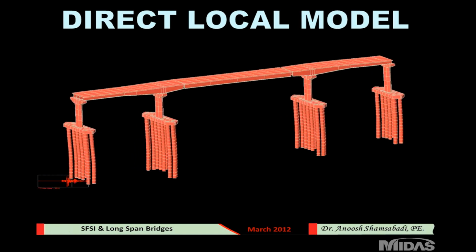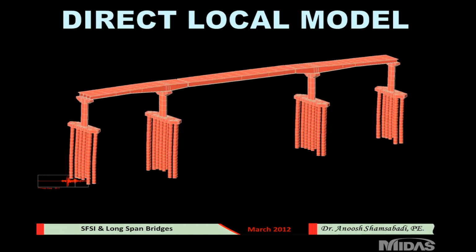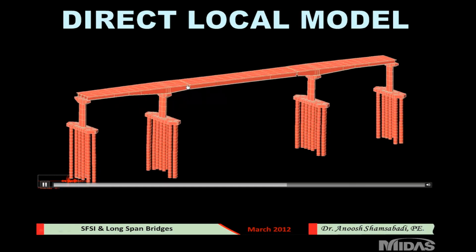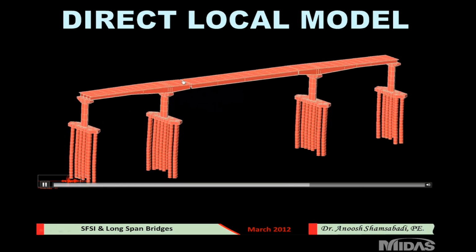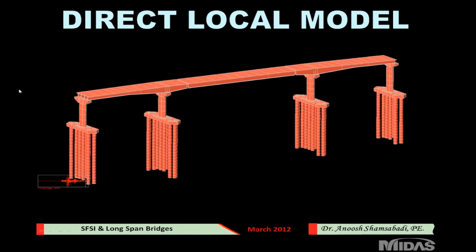When we looked at the acceleration record of the bridge, we saw a lot of spikes at this location. When you look at the model, you can see how this span is hitting the two cantilever portions, and that's one of the reasons we're getting a lot of spikes in the recorded motion, which I don't have here; for the interest of time, I didn't show it.